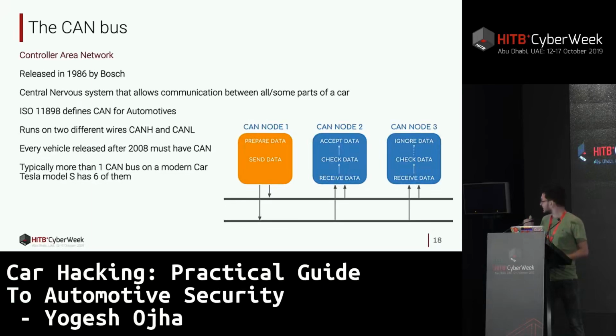This is when the boss came up with the idea of the CAN bus, where you can just have 2 wires, CAN high and CAN low, and all the components are going to get connected to each other using just these two wires. So it integrates all of these complex components in such an elegant way that all of these components can interact with each other at a very fast data rate. In the CAN bus, there are just 2 physical wires that connect the dashboard to the engine to the steering, and all this sort of stuff.